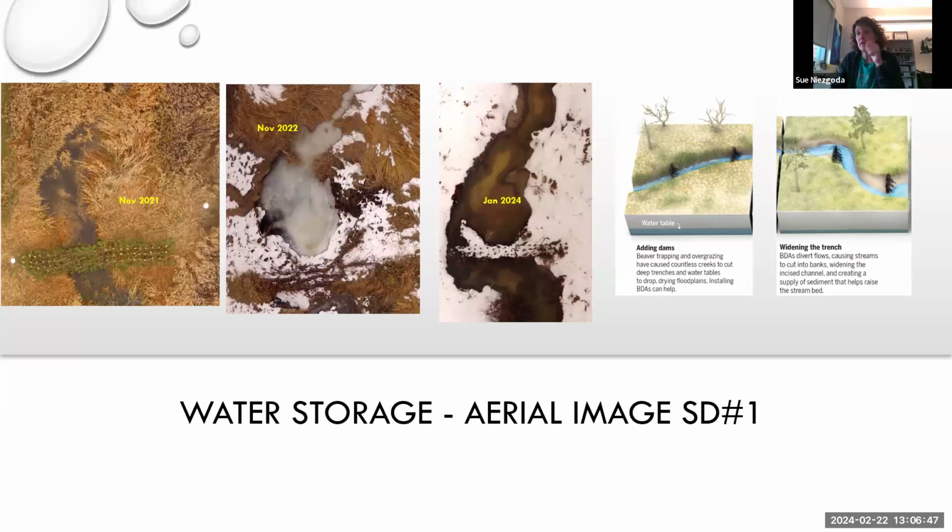They aren't necessarily creating the ponding that we originally intended, but they are creating this sort of first phase of what these beaver dam analogs should be doing, right? They're attempting to widen, allowing for channel widening, as well as increasing sinuosity, which can also then eventually lead to sediment deposition, right? Because you're releasing that energy by widening the channel. So we're getting some initial, and it's only been 2 years as well, reaction to the beaver dam analogs in a trajectory that seems positive, right? With at least decreasing stream energy and hopefully eventually creating some more sediment deposition along with phosphorus.